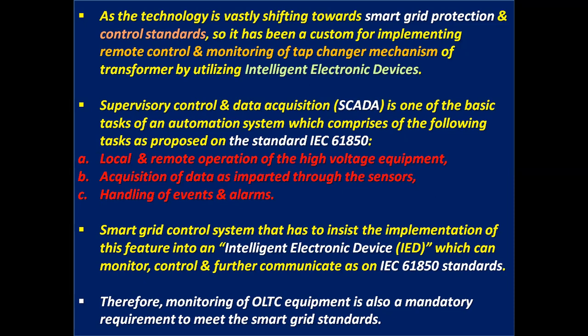The smart grid control system insists on the implementation of this feature in an intelligent electronic device, which is called IED, which can monitor, control, and further communicate as per IEC 61850 standards. Therefore, monitoring of OLTC equipment is also a mandatory requirement to meet the smart grid standards.